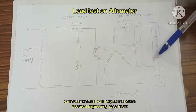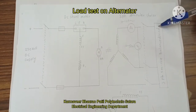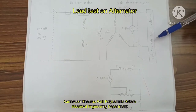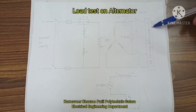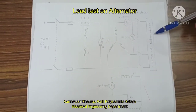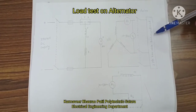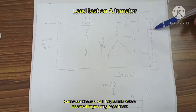In this case we are going to connect the variable load on the output of the alternator. This is a three-phase variable balanced load. So we are connecting all three types of load: star connected resistive load, then inductive load and then capacitive load, and we will be conducting three different setups for three types of load variation.